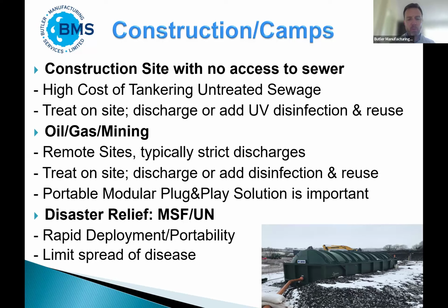Oil, gas, and mining sites are typically remote and they come with strict discharge standards. For example, we did a project with Bechtel in the Algerian desert, and obviously it's not populated or anything like that, and you think you could just discharge, but there were strict environmental discharge standards, so they installed packaged sewage treatment plants on their camps, which are about every 500 miles, and they disinfect and reuse the sewage to cut down their potable water use as well, which in the desert was really important.